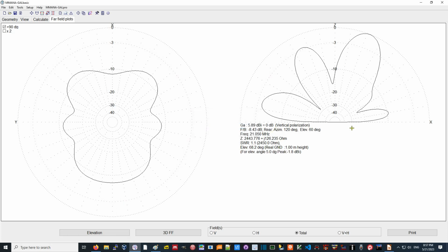So now the pattern's changed a little bit. Well, yeah, because now he's essentially taken the cross section at the 5-degree mark over here. This one over here is still pretty much a cut across, like a chainsaw took to it. But this one right here now is telling you that lobe right there, remember, the closer to the edge there, the more gain you've got, and it's actually quite good. So if we go and use the mouse, we can see over here now that at an azimuth angle of say minus 180, which is going in the minus x direction, you will have a gain of minus 1.8 dBi. Now the interesting thing here is that the gain is relative. So this program really gives you an idea of where your highest gain is, where your lobes are, where your highest gain is over there, and so on.